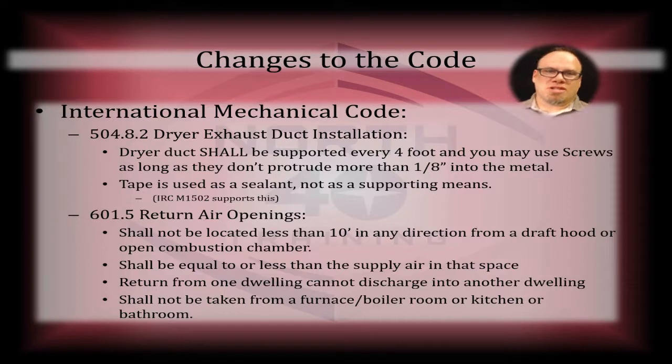A few code cycles ago, the definition of bathroom changed from a room to a space that has a basin, one other fixture. What's a basin? A sink, basically. Okay, so you have a sink and a toilet, or a sink and a shower. And, you know, the idea was not to make things complicated. The idea was to accommodate the more modern style bathroom areas, right? You go into a hotel, you've got the shower and the toilet in one room, and you've got the vanity and the mirrors and all that kind of stuff in another room. So 2 people can be getting ready at one time. And that was the intent of the code, to accommodate that and make sure that things were wired, plumbed, and mechanically speaking, installed the way that they should be. Right? That makes sense, hopefully, to you.